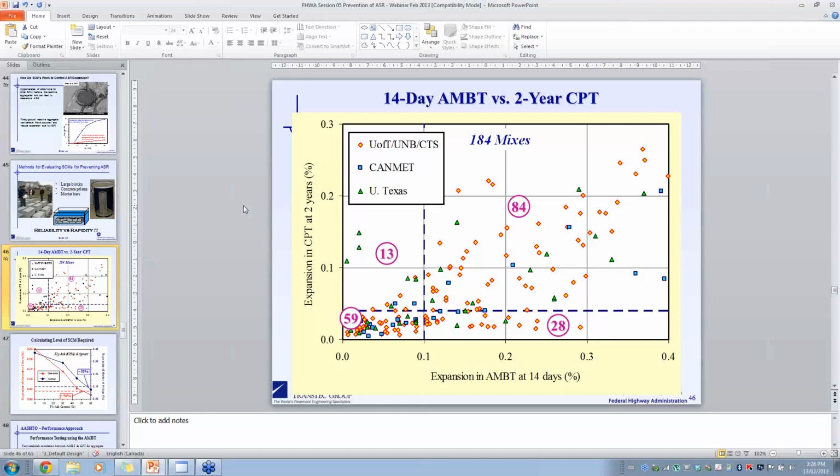With DEF, you're generally looking for evidence of expansion of the paste, gaps around aggregate, maybe or maybe not filled with ettringite. If you find some of those features, it's an indication that DEF might have taken place. To try and determine which one happened first, if you can be sure they both happened, I think it's unlikely you could determine which one came first. Although in my experience, alkali silica reaction usually happens on a much faster time scale than DEF, so it's most likely the ASR came first if they're both present. I'm not sure that answers the question.